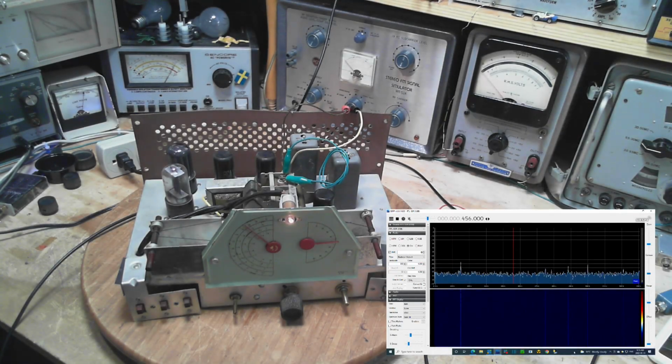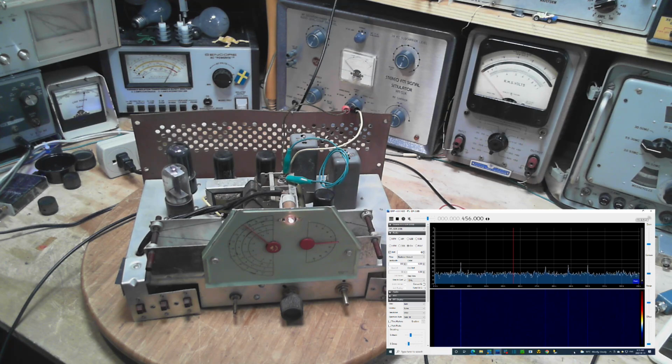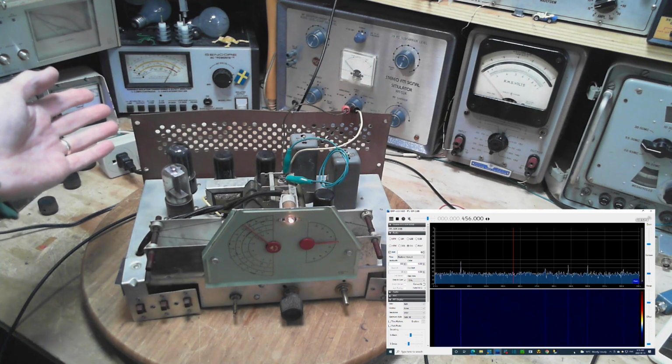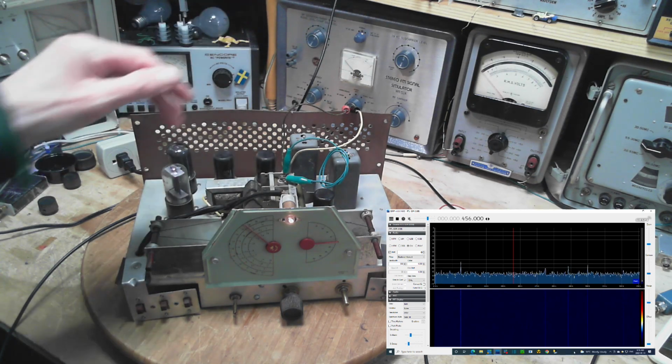Well, wow, okay, so a light bulb has come on in my head. I always thought when you have an IF trap, which is a simple circuit to try to snuff out the IF frequency at some point in the radio, usually right on the antenna, the main objective was to keep the local oscillator from going out of the radio.